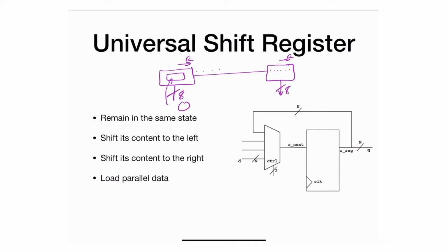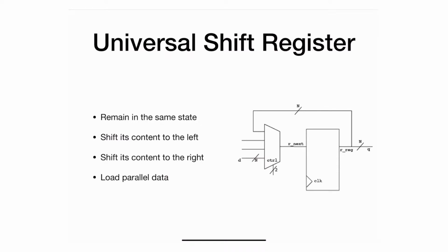We're going to see it when we talk about communication protocols, but for now what I want to do is implement this particular system in here. So how do we implement it? Well, this particular block should help us. You're going to see here I have exactly 3 parts. I have a part in here, which is the combinational circuit that specifies my next logic. I have another one here which specifies the register. That's the state of the system, and technically the output in here is just the status of the register. There's no circuit or anything.